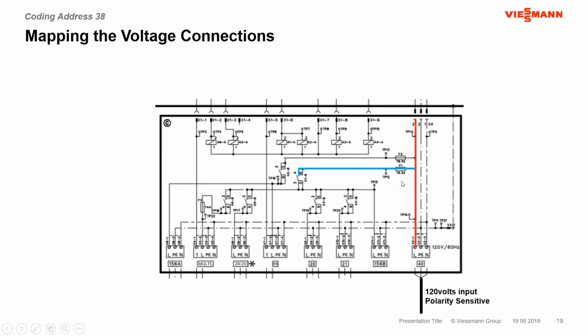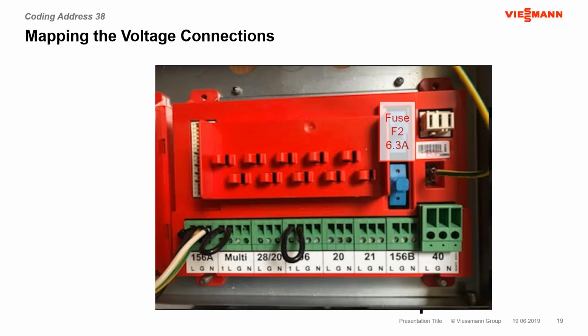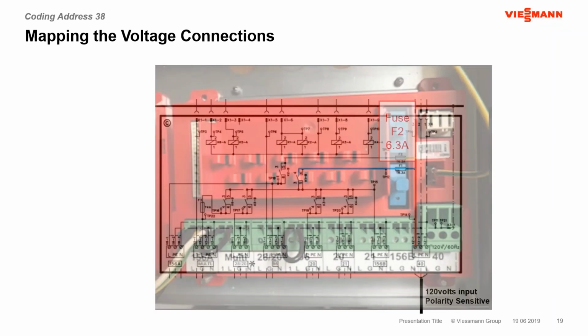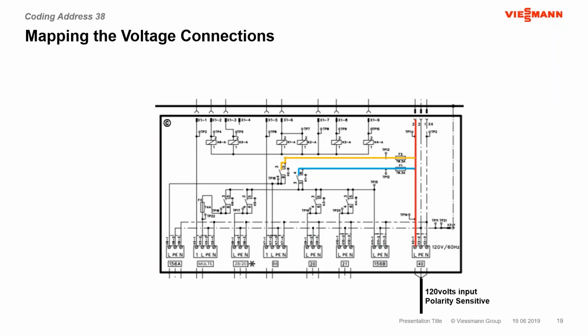So now the power is sitting there waiting for this contact to basically be made so that power can move through the control further. The next area where the power branches off, it hits the F2 fuse just above, the exact same fuse, 6.3 amp. Moves through there as long as that fuse is not popped, it's closed. And it sits again waiting for another relay, or basically a relay here to close to allow that power to go past that particular point.